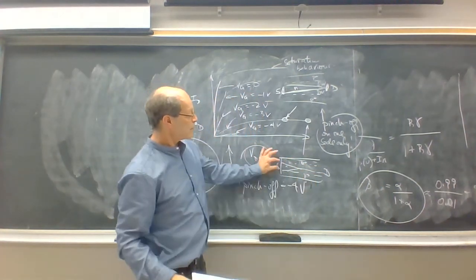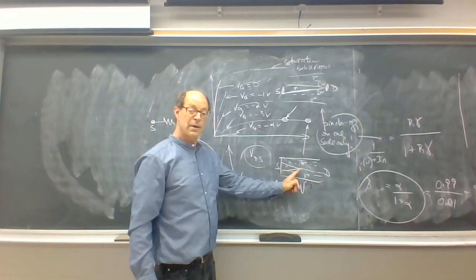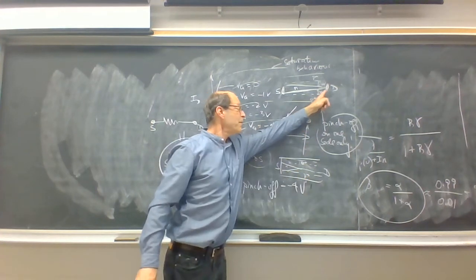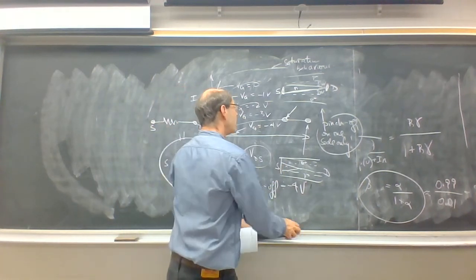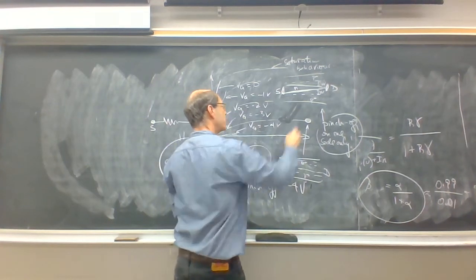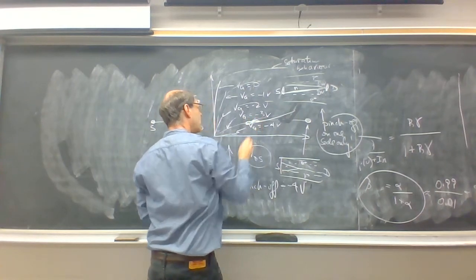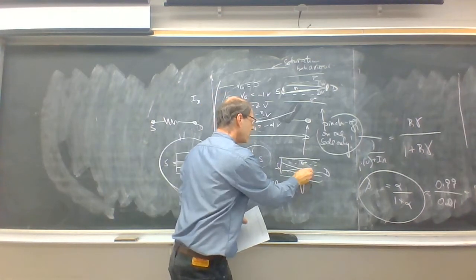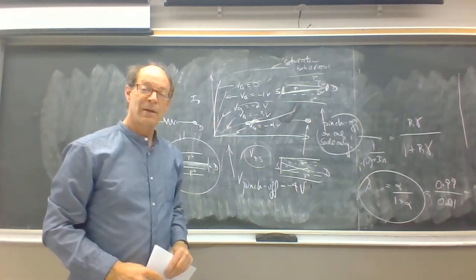So what you'd see now is that the channel would pinch off not at the drain, but well before the drain. So pinch off there at the drain, pinch off here well before the drain. So actually, this point here, where I drew the original pinch-off condition, should have been more like there. And then as I move along this curve, that pinch-off point is moving to the left.